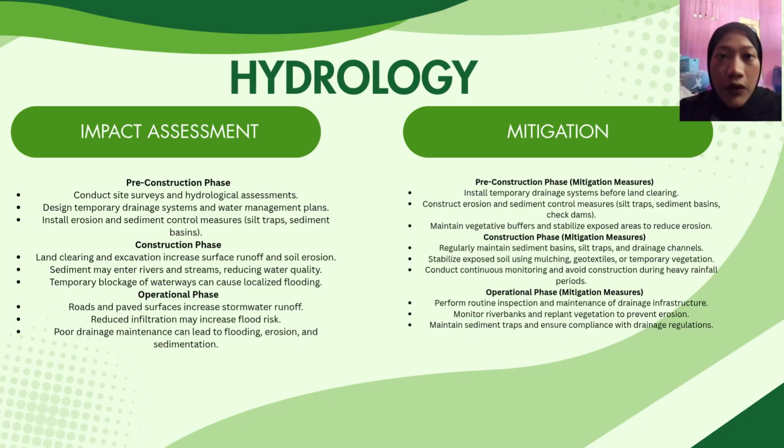Pre-construction phase: first conduct site survey and hydrological assessment, design temporary drainage system and water management plan, install erosion and sediment control measures, silt trap, sediment basin. For construction phase, land clearing and excavation increase surface runoff and soil erosion. Sediment may enter river and stream, reducing water quality. Temporary blockage of waterway can cause localized flooding.